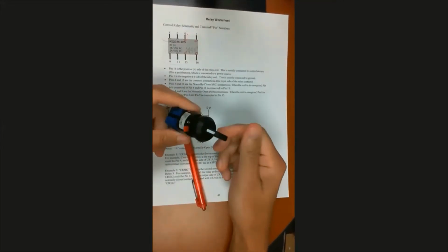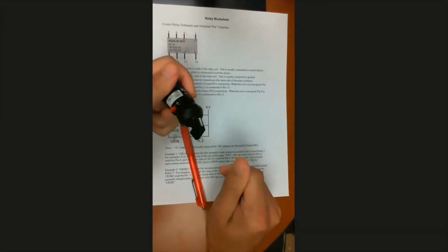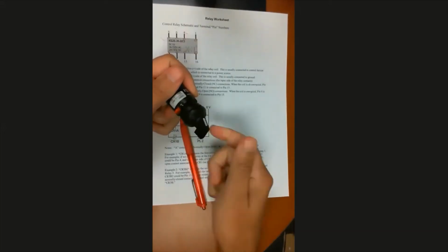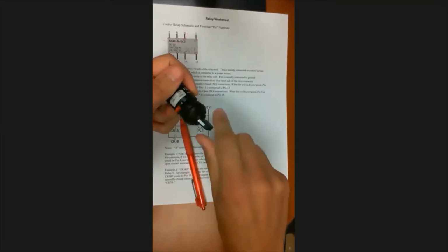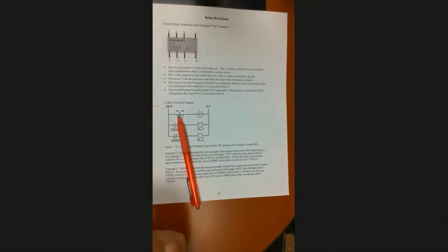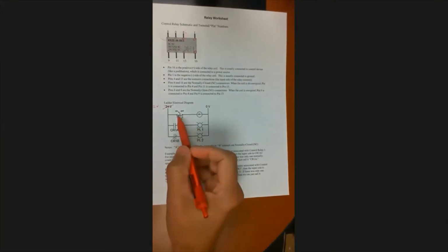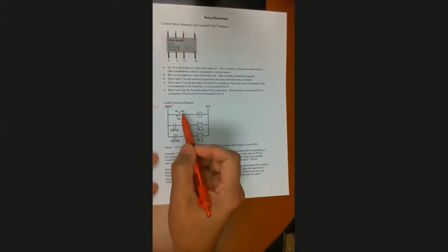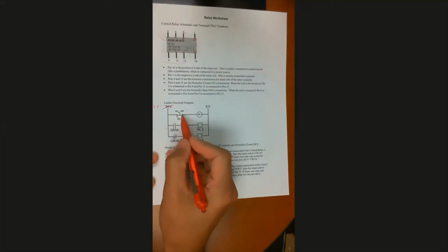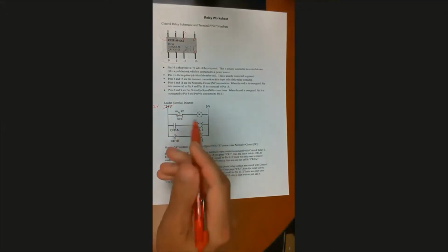So anyway, this is a selector switch. It doesn't have a normal position, so it doesn't spring back or anything. You move it to a position and it stays there. So that's what a selector switch does. Typically, one side of the selector switch would be designated as the on side and the other would be the off. So the way you draw this is with 4 connection pins, and that's actually true.